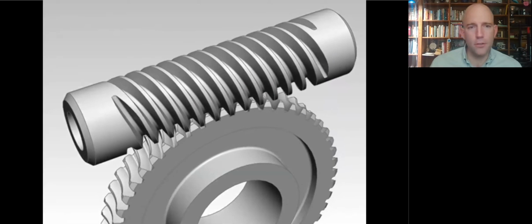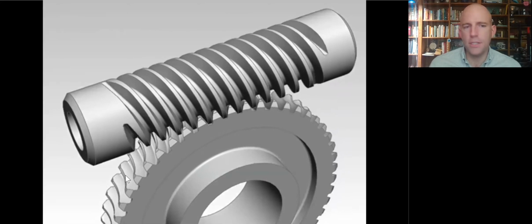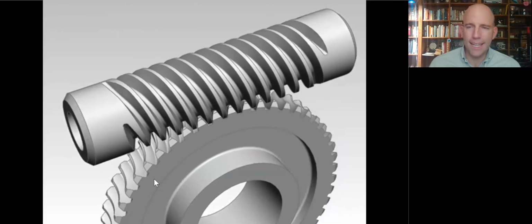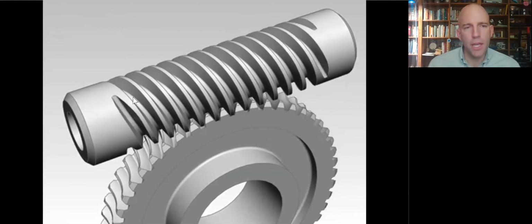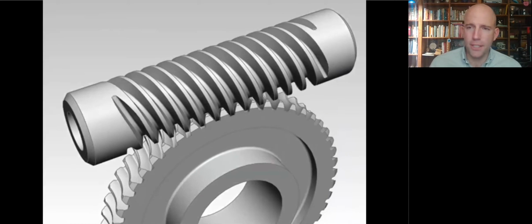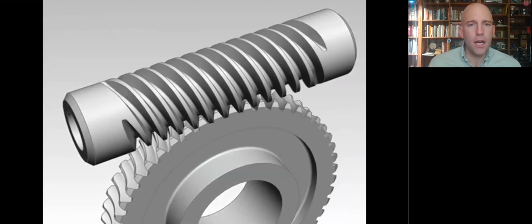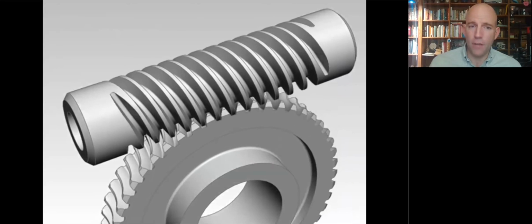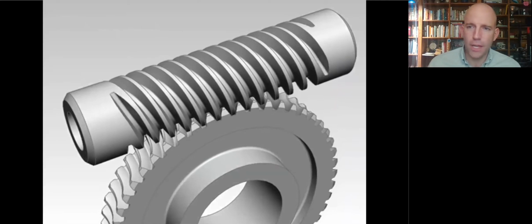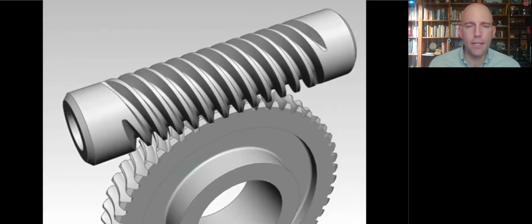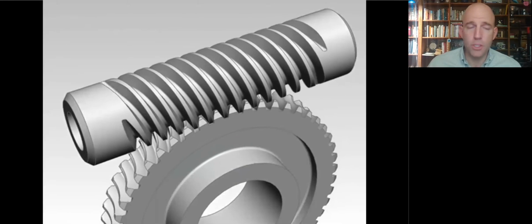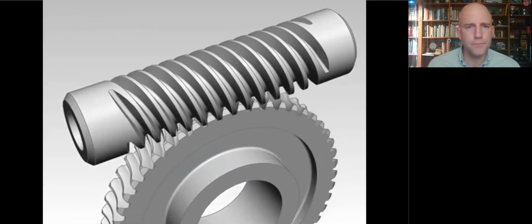This is a worm gear. A worm gear looks similar to a spur gear, except the teeth are shaped a bit differently. And instead of interacting with another gear-like shape, it interacts with this screw-like shape. The screw here is going to be the driving element. These are generally not back drivable. And the cool thing about a worm gear is that you can achieve a really high gear ratio in a compact form. In the topic reading, we tell you a little bit more about how to estimate the friction losses, which tend to be quite a bit higher for worm gears.